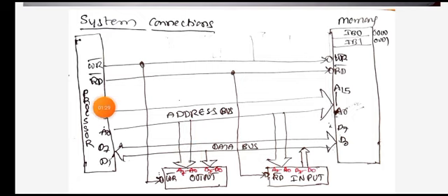When you look at the processor's function, it will issue sequential addresses on the address bus and a read signal to the memory. All the instruction bytes are transferred through the data bus, through the data pins of the processor, and enter into the processor. All the instruction bytes are executed sequentially. The processor sends sequential addresses 000, 001, 002 like this. In this way, all instruction bytes are transferred through the data bus, enter the processor, and all the instructions are executed